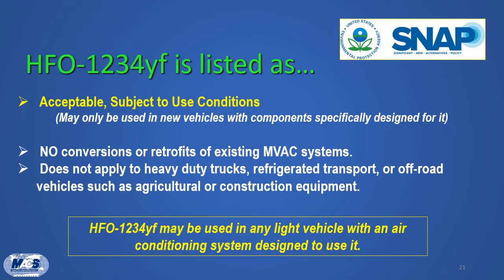So how does EPA keep track of all these refrigerants? Well, they have a list, and it's called the SNAP list, or Significant New Alternatives Policy. One of the new mainstream refrigerants that's on that list is HFO 1234YF, which is listed as acceptable subject to use conditions, which means it may only be used in new vehicles with components specifically designed for it. Okay, so what does that mean? It means that no conversions or retrofits are allowed for any existing MVAC systems.